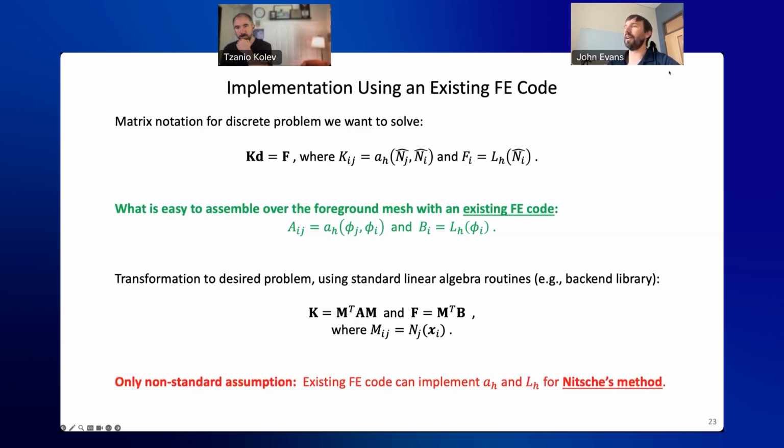So we actually build preconditioners based on K and not A. Now, if you don't want to fully assemble K, there are other approaches that you could certainly investigate, but we haven't done that at this point. So we looked at standard block Jacobi, block ILU type approaches in this project.